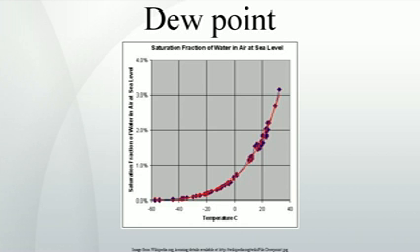Measurement. Devices called dew point meters are used to measure dew point over a wide range of temperatures. These devices consist of a polished metal mirror which is cooled as air is passed over it. The temperature at which dew forms is, by definition, the dew point. Manual devices of this sort can be used to calibrate other types of humidity sensors, and automatic sensors may be used in a control loop with a humidifier or dehumidifier to control the dew point of the air in a building or in a smaller space for a manufacturing process.